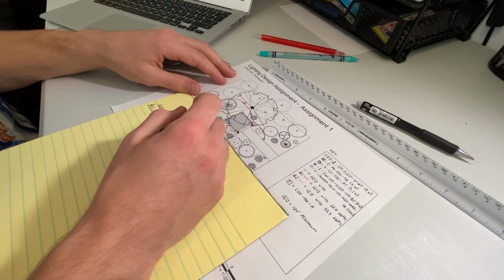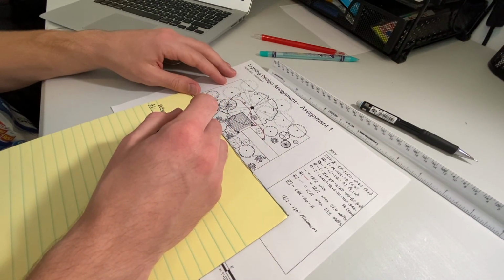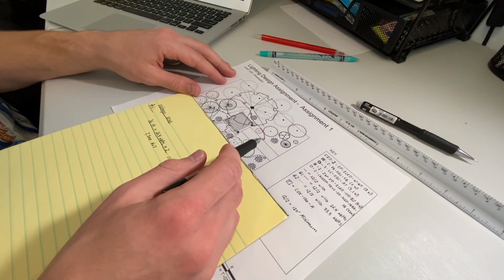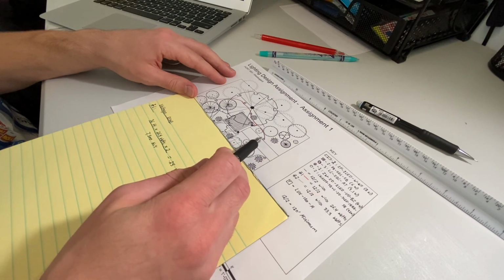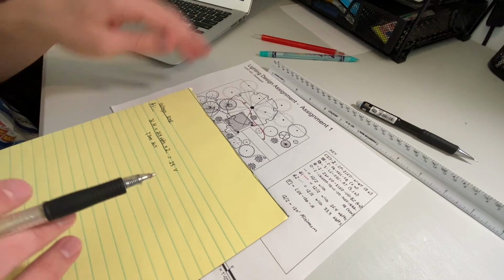Once again, that means if the transformer is giving out 15 volts, which it is, at this furthest light, it's only getting 14.75 volts, which is fine because it's within the parameter.